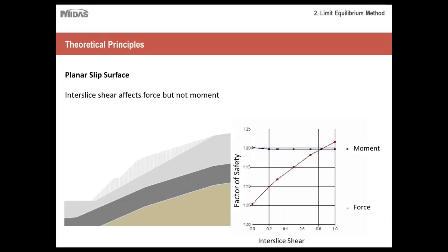Once again, depending on your project conditions, this may or may not be a suitable choice of shape for you. If you're expecting little to no shear forces acting normal to the slope itself, then this may be of use to you. Whereas if you're expecting a significant amount of moment acting on the slope, that would be another thing to consider that would make this shape more effective for you, since it takes moment into account.